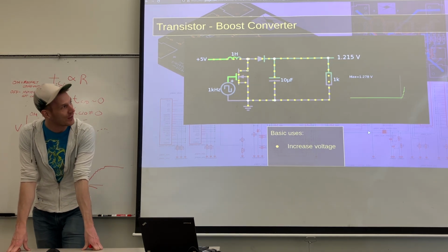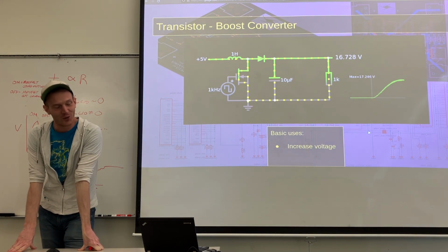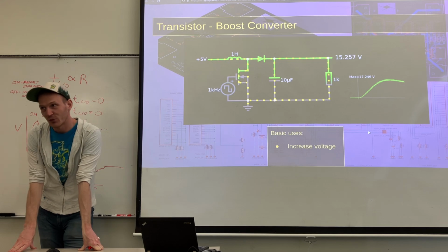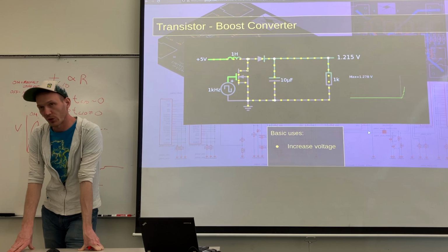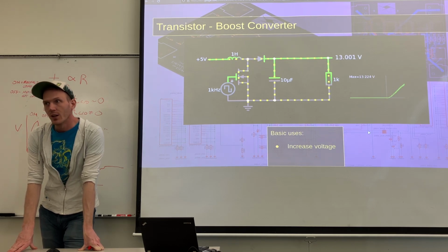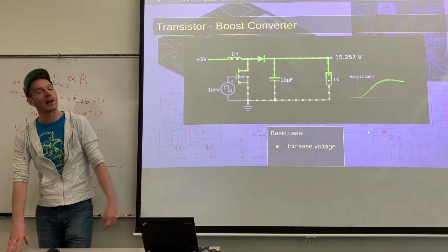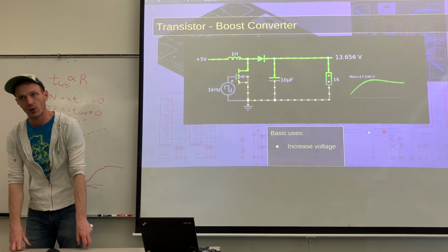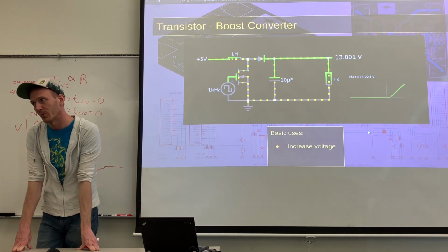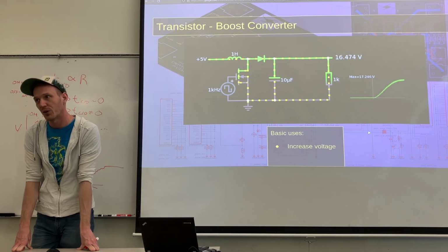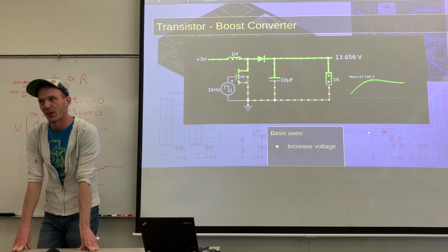Okay, so this is probably the last easy to understand circuit that we'll go through. If we have to step up our voltage to supply our reaction wheels for the CubeSat and for the weather balloon, this is probably what we use. Because you're just shorting the ground, these are kind of low efficiency, but for example, these apparently are used in Toyota Priuses to go from like 230 volts to 500 volts for their motors. So I guess if Toyota doesn't think the efficiency loss is that bad, then I probably shouldn't be too worried about it either.